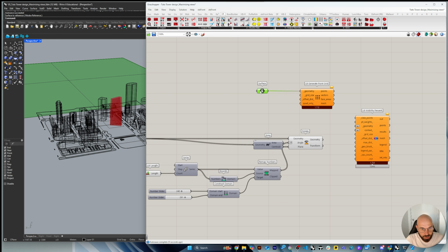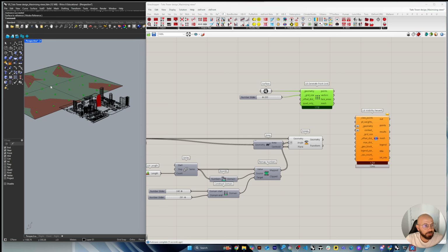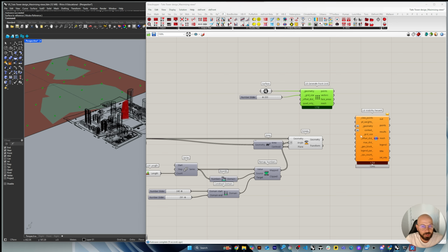So I'm just going to set it up here and call it ocean surface. And then my grid size, I'll set it up as 100. Let's see, 200. 200 should be okay. Basically, the more points you have in the grid, the more accurate it might be, but also the more time it's going to need to process.